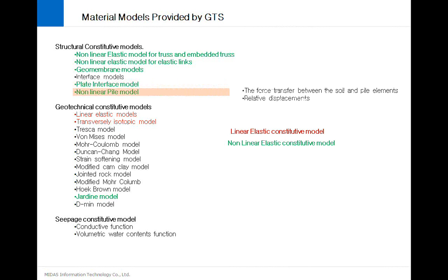We have the nonlinear pile model, with the help of which you can account for the force transfer that is taking place between the soil and the pile elements, as well as the relative displacement that is taking place between the soil and the pile elements.